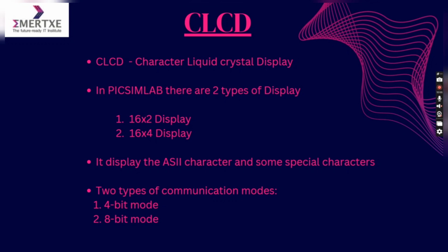The advantage of 4-bit mode is that it requires fewer pins from the microcontroller, while the advantage of 8-bit mode is that it is faster and simpler. In our project, we'll use a 16:4 CLCD display in 4-bit mode to show the status and setting of our microwave oven simulator. We'll use the CLCD library provided by PiximLab to initialize and control the display.